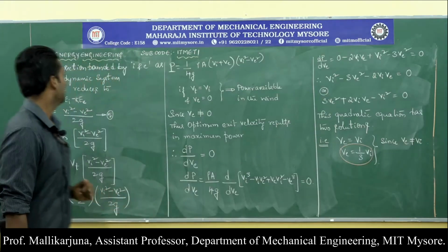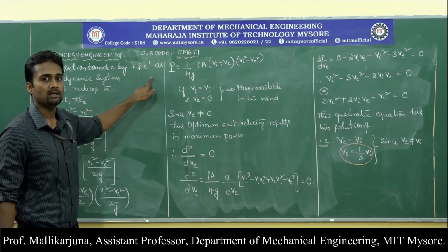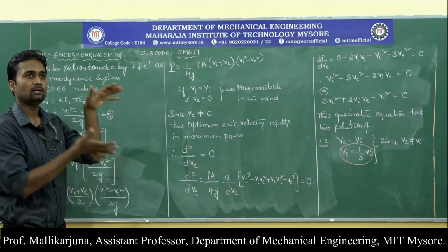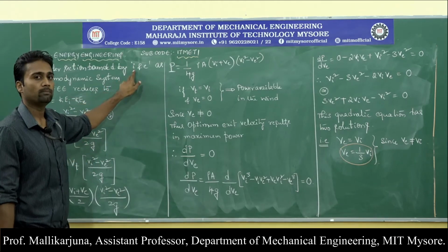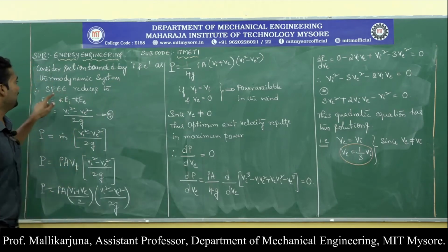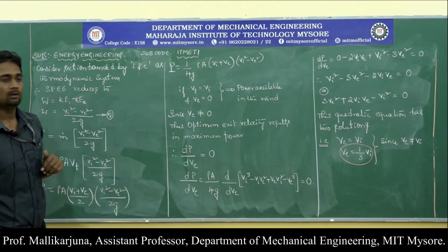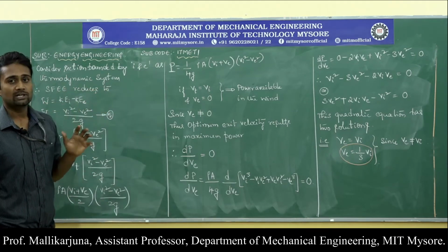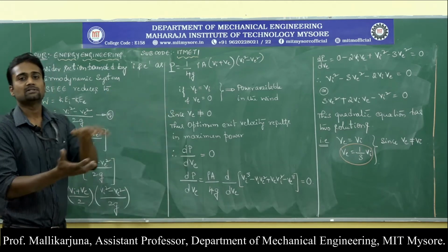Okay. Now consider the entire section bounded by I and E, in the sense the upstream section, blade width and the downstream section. That is the section bounded by I and E, as a thermodynamic system, and apply the steady flow energy equation to that entire system. We know upon applying the steady flow energy equation, we have already applied this equation for segregated sections.